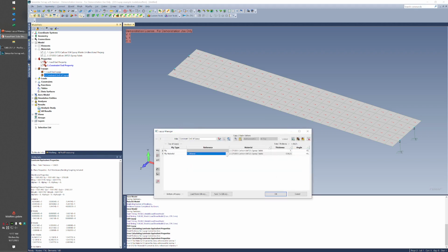We can go back over here and change this. We've got ply material. We can always go back to the drop down, and there's our ply demo. It automatically filled out the material and thickness for us. Another thing we can do, through this reference, is add a layup. We can just insert an existing layup that we might have. So let's insert that one layup that I've already done.